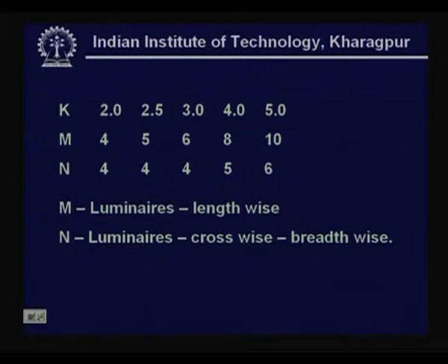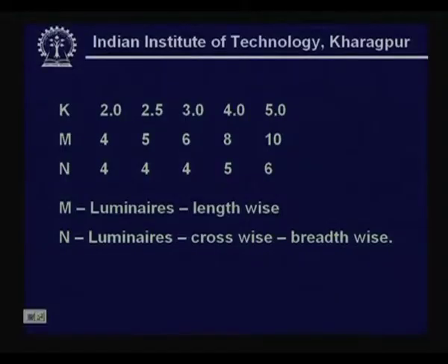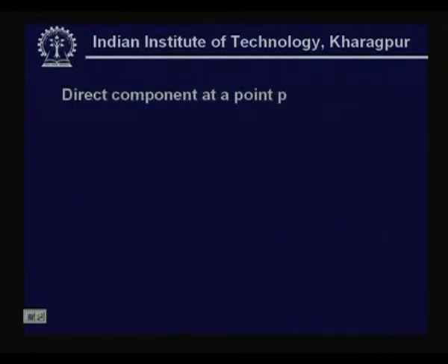I have not said lamps, because again, depending on the service, depending on the illumination required, in a single luminaire I may have a single lamp, or a matrix of lamps if they are incandescent lamps, or a matrix of lamps if they are compact fluorescent lamps, or a set of fluorescent lamps, minimum being 2, and these days we do have 3 and 4 provided. Okay. So, this is one thing.